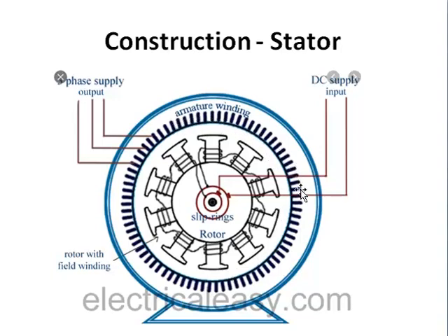So that armature winding is placed inside the stator, and this armature winding is a three-phase winding, and it is star connected. If you remember, in the star connection one end of all the windings is joined together, so that is the neutral point. That point is connected to the ground, and the other three ends of the phases, R, Y, B, you can see these are the three ends of those three windings. So these three windings are connected here in a star fashion, and that forms the armature winding, which is on the stationary part of the synchronous generator, and it is called the stator.